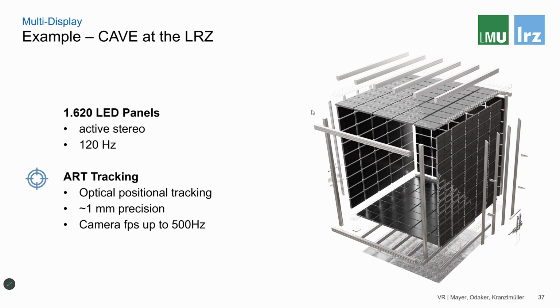Basically what you do is you mount a number of cabinets next to each other, you clip the panels in, and that allows you to get a continuous screen without any bezels or borders in between. And you set up any shape and size you want. The resolution is then determined by how far two of your pixels are apart. So you buy these LEDs with a so-called pixel pitch.